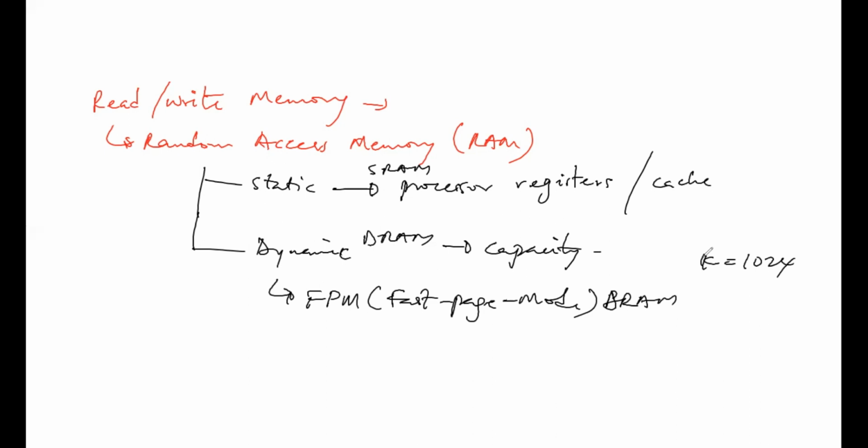So the fast page mode DRAM represents part of the memory with the same row address. If you want to access a page, we specify the row address once. So we can read the bits in the specified page by changing the column address. Since the row address is not changing, we save on the memory cycle time. All jargons you know before now.